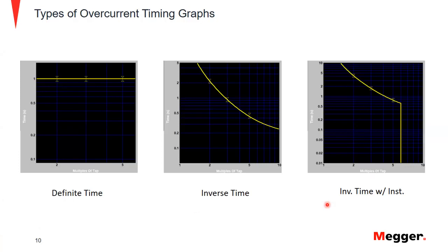The instantaneous element that's tied into the inverse time characteristic is very effective in reducing operate times of severe faults. They don't offer any selectivity because they do have different characteristics, and they're instantaneous for a reason, because we want to make sure that we get the fault current off the device in the yard as quickly as possible to minimize damage.